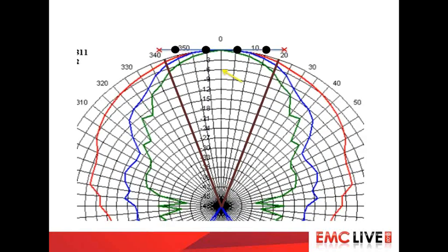So we look here again at our polar plot, and if you remember at 0 degrees where it hits the calibration plane, that is our maximum power density, that is our maximum volts per meter. And if we bear in mind that it cannot exceed 6 dB higher than that, then I marked the 6 dB there, if you look carefully, with a yellow arrow. The first circle is 0, then the next one down is -3, and then I mark with the yellow -6 dB. And if we draw that line in, pretty much we've got our limit.